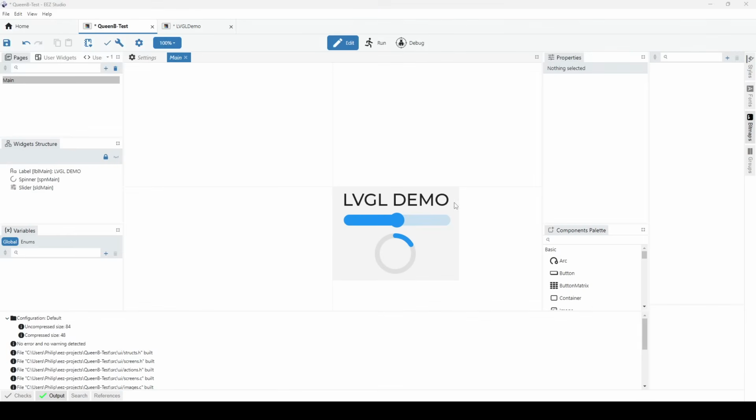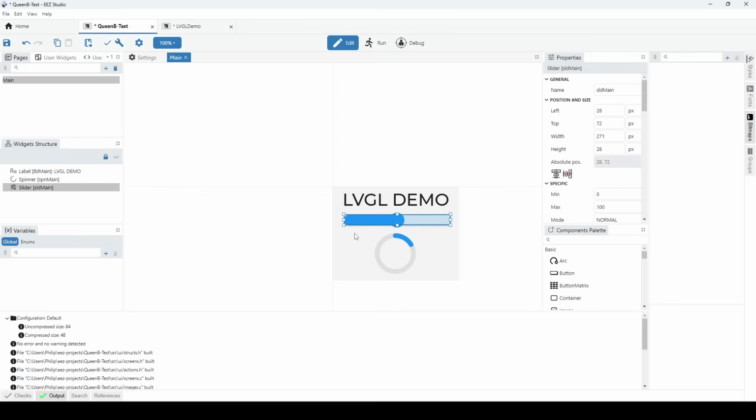Now, of course, with a UI, you want to change maybe the elements. You might want to change the slider position. You might want to change the text or switch to a different screen, which shows different elements and different widgets. And of course, with LVGL, you can do that quite simply. You can either access the elements or these widgets directly and change their properties, for example, changing the actual position, their location, and so on, just programmatically, or you can tie that to the LVGL input controller as well. For now, for the sake of simplicity, just to show you that this is possible, we can scratch the surface on this, we'll just do it programmatically.